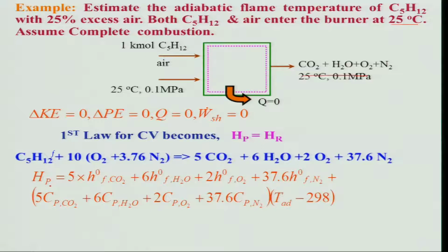Then we can find out what H_P is. It has one term, 5 times the heat of formation of CO2, and 6 times the heat of formation of water, and likewise for oxygen and nitrogen. Besides this, there is the sensible enthalpy term. Here we are saying that Cp remains constant in this example.